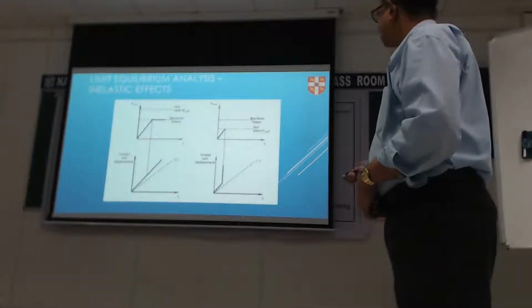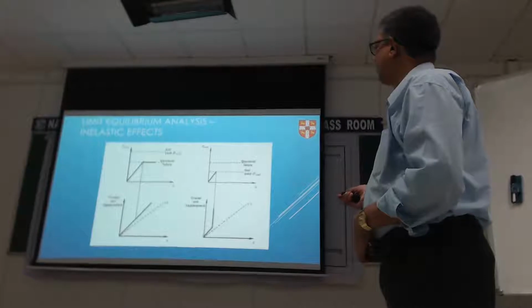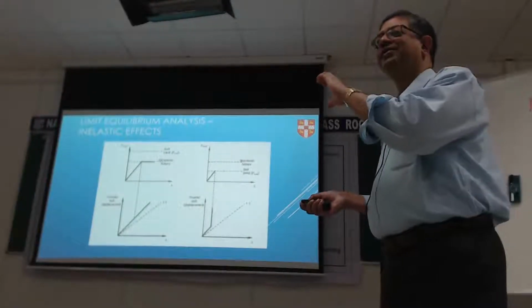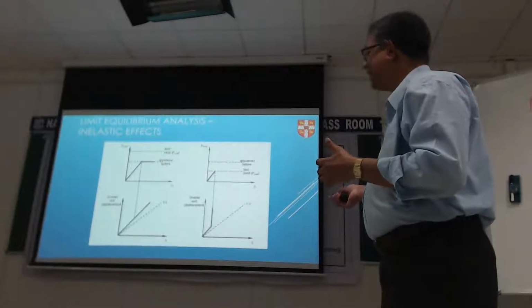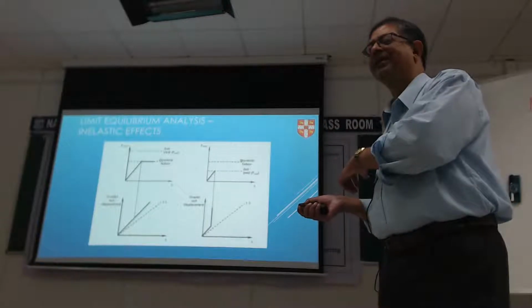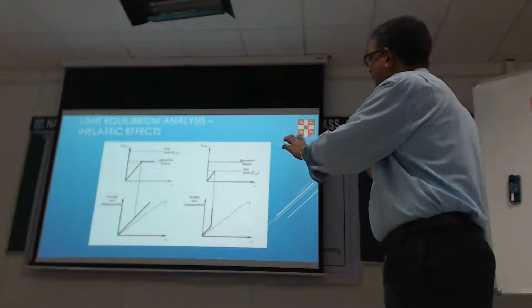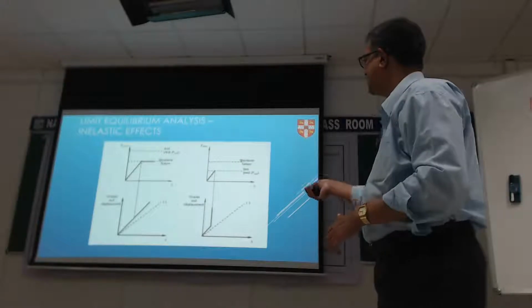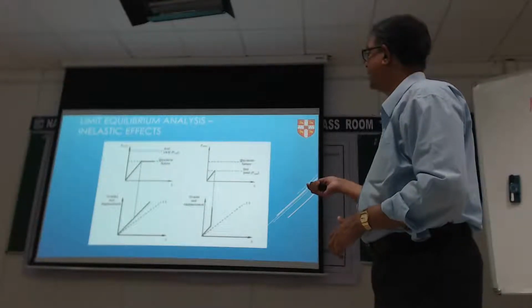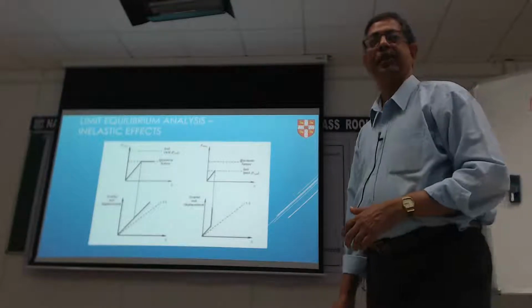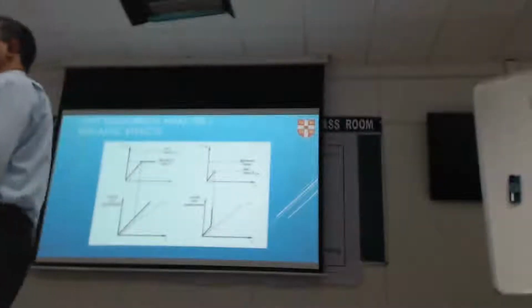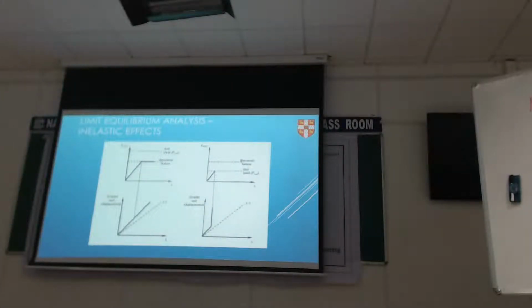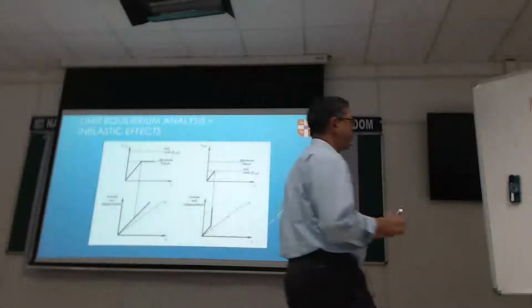Also, if you combine that with weak crust compared to strong crust, then you could yield the soil, not make the structure suffer. Both those extra things you can handle by changing where you draw your soil yield relative to structural yield lines. So some inelastic effects can be included. So if you take one more minute on this, what we're saying is, if I can draw the plan view,